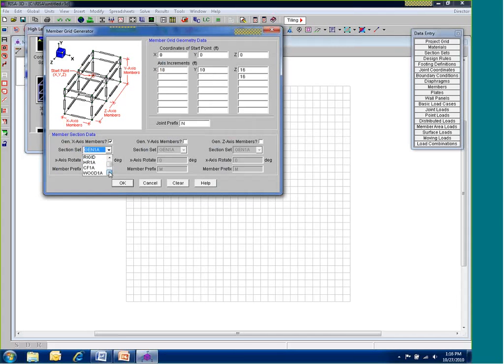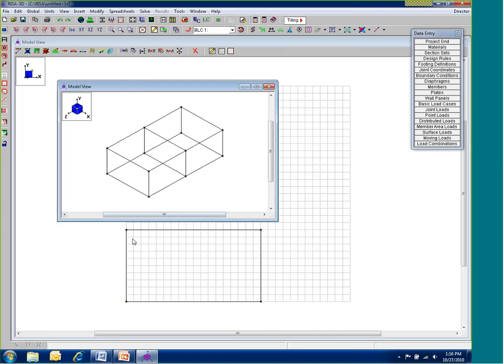And I'm going to choose those to be my joist members. And then in here, I'm going to turn my Y-axis members to be my columns, and I can pick this from the list. And then I can define the Z direction to be my girders. So once we lay all this out, I'm going to just say OK. We see we have a kind of a start of our frame. So it's just the basic beginnings of what our frame is going to look like.